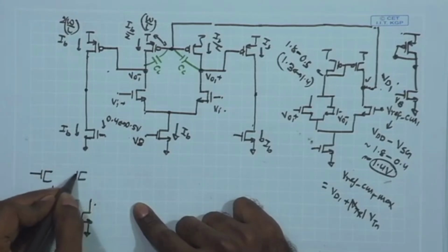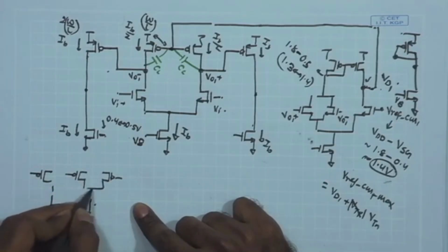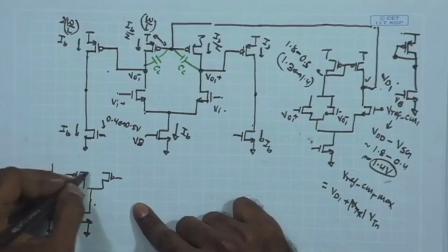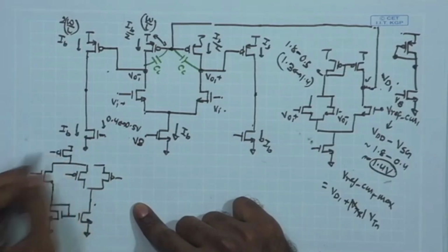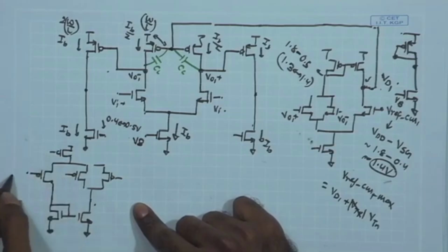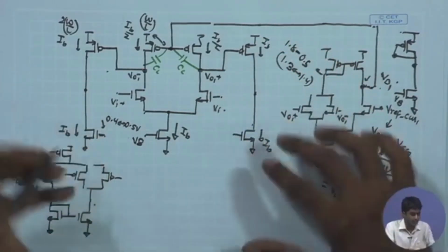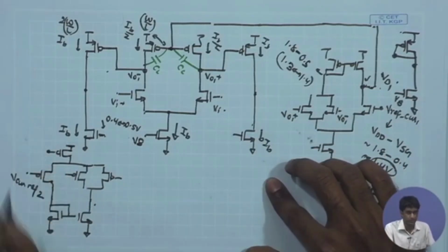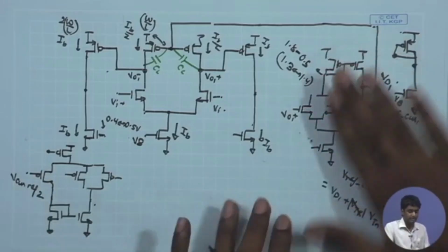This is the reference one, and this has to go on the other side. I'll do that, and you have the PMOS current source. So here I can put my VCM ref 2, which is the output common mode reference point. Now what should be the output common mode reference point? This is anyway a DC bias, so from the AC point of view, I can put it at AC ground. So this is again my differential amplifier, the same error amplifier topology.